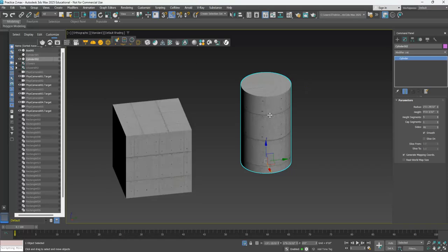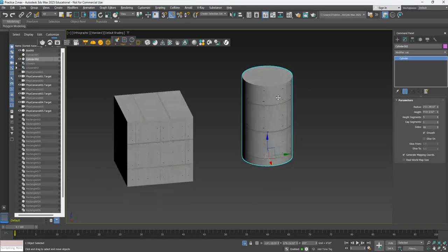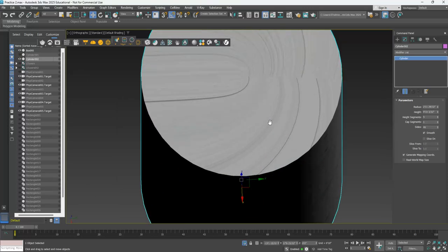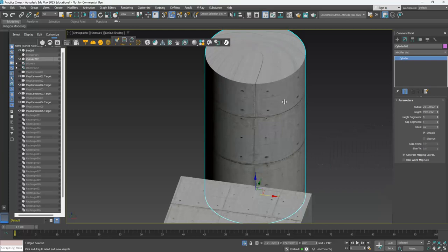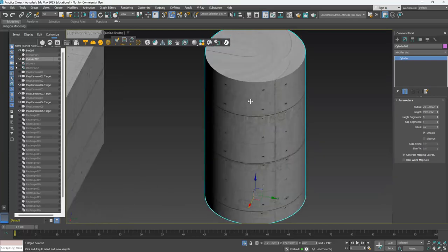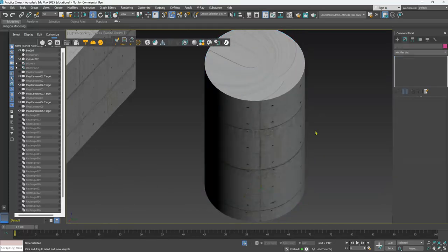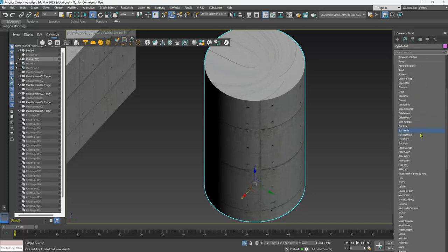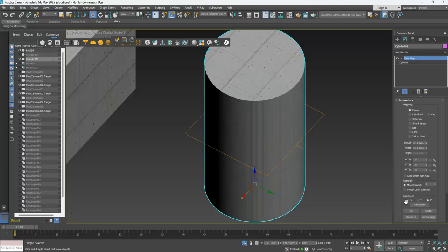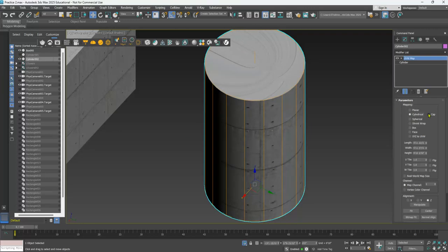So how does it look right now with this shape, without any applications? Looks okay, somewhat, but everything's gonna stretch because it really has no idea how to treat this object that we have, right? So again, select it, and we'll always apply two modifiers. We go again to UV map, and what am I going to pick this time? Cylindrical, right? And cap, right? Over here. In case there's no top, we can remove the cap, but we have that.